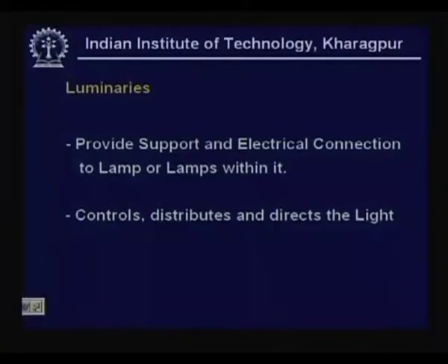That is what we call the control gear, and the luminaire may have provision to include those things within its container. Now, therefore, primarily it provides support and enables electrical connections. It says lamp or lamps, that means in a single luminaire I may have more than one lamp. One could in fact look at the required amount of illuminance on the object surface and thereby work out how many lamps are required and accordingly put them.